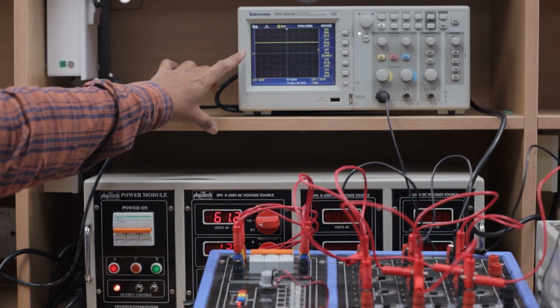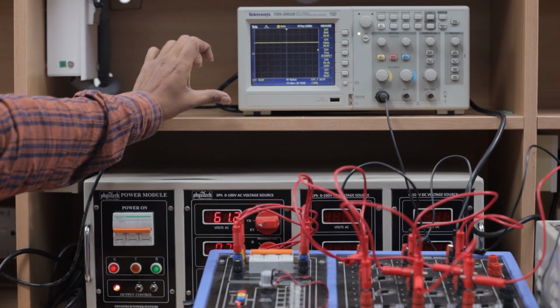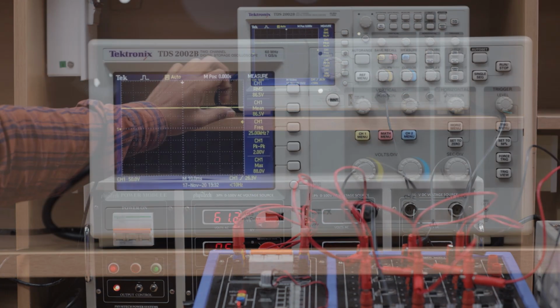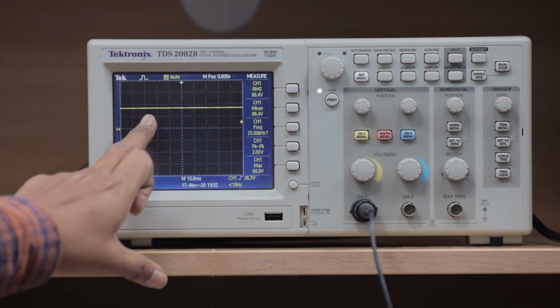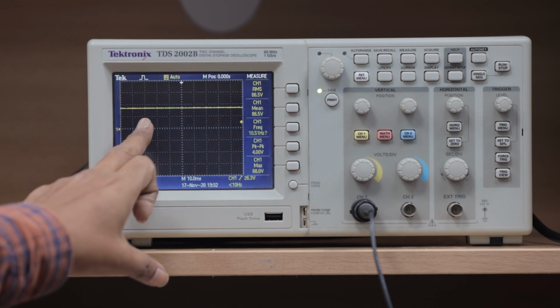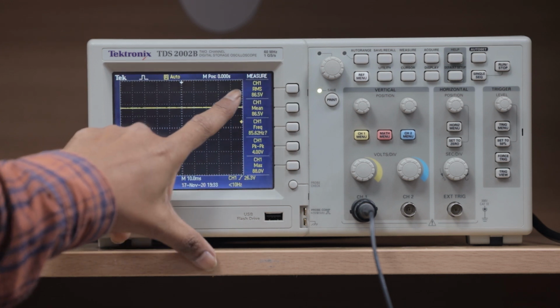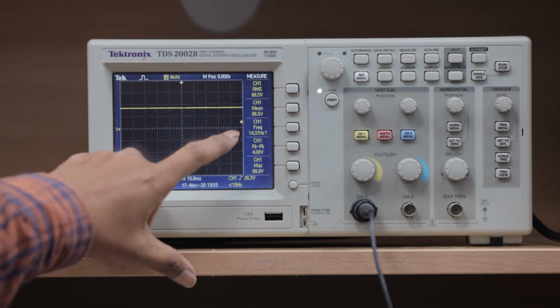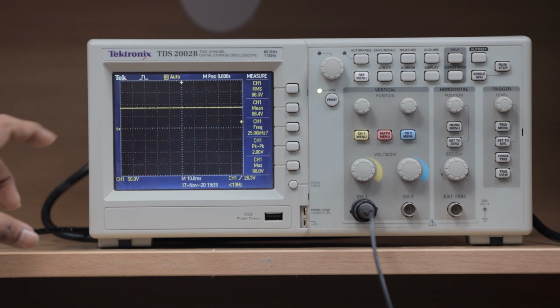Now, since we are using a capacitor, you get a pure DC output voltage. Now you are measuring across the R load output, and you get a straight line. Why? Because we are using an RC circuit. The capacitor value is 5000, so you will get almost a DC output. From this you will measure that the RMS voltage and mean voltage are all the same. Why? Because in a DC component there is no frequency value, so the mean and RMS are the same.